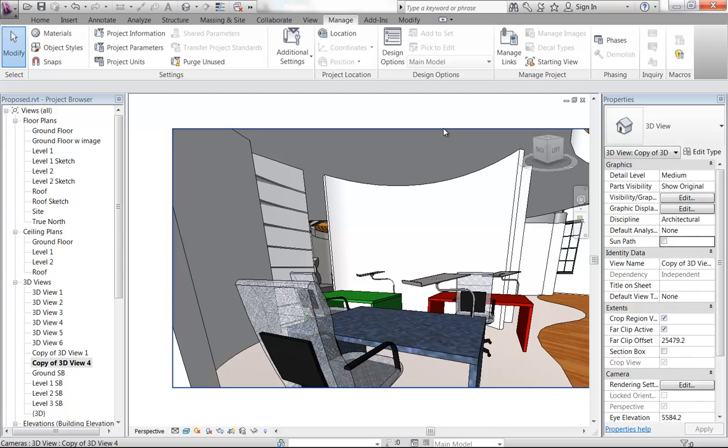materials with a bit of depth like fabric and things like that, which you can do in Revit, all of those things. But those more complex materials have issues, especially things like glowing materials and also semi-opaque materials, semi-transparent and translucent materials do tend to have problems with Revit. That's why I want to show you more about those in 3ds Max. But let me know if you're looking at doing especially self-illuminated materials, glowing materials in Revit, and you're having trouble. Let me know, and I can maybe look at that with you individually.